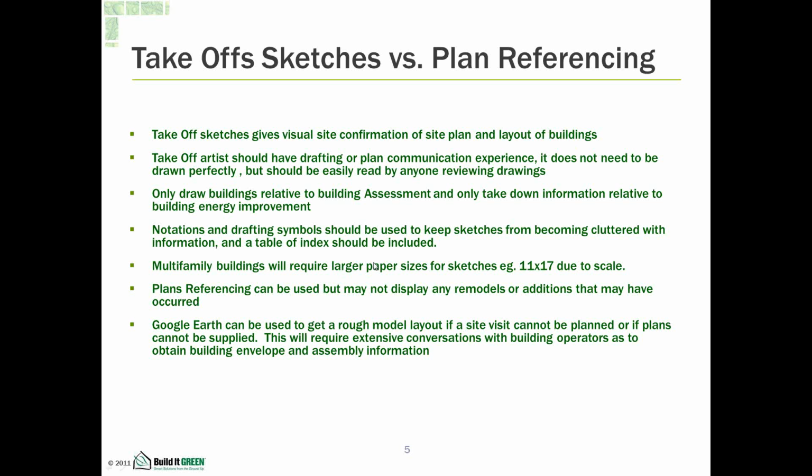And also, sometimes I use Google Earth if I get called into a project pretty late and they don't have anything as far as plans. I'll use Google Earth to get a floor plan, and then use the street view to get a good understanding of what each elevation looks like. And Google Earth is nice because it has a little scale metric on the bottom right, and you can use that to scale out the drawing and give a good rough drawing. It doesn't need to be perfect, like I said, but just to give you a good basis, and then again follow up with a site visit when the time comes. But if you get called on a project late, Google Earth is great to use.